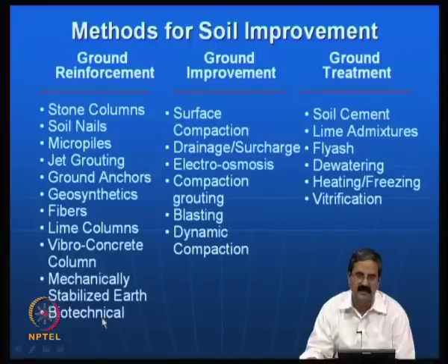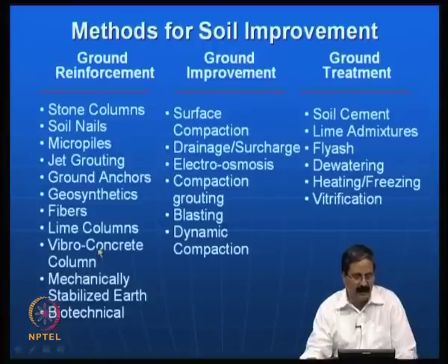Now, even biotechnical stabilization. In fact, slopes are getting eroded. So, what do we do? We just use some grass on the slopes which have erosion, and then the slope profile will not get eroded. Gully erosion is a classical problem, because of the influence of water which forms on the slope surfaces, you will see gully erosions. But if you have grass and some other enzymes, biotechnical stabilization is possible. This is a very challenging area, and people have been working on it to a large extent nowadays. That way one can put some of these topics under ground reinforcement.